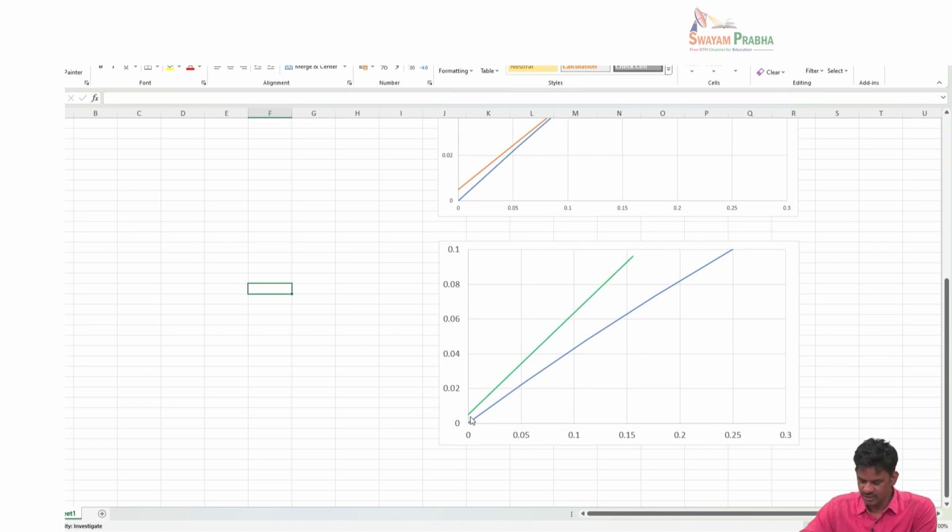Okay, so green one here, this point here is y1 and x naught. X naught is 0, so that's why this cuts at the y axis. Okay, so this will be like 0.005, and the other point here is based on the operating line, LS by GS value of 0.585. So y axis somewhere here is something like 0.074 or something like that, and here this will be 0.111. So the two ends are known.